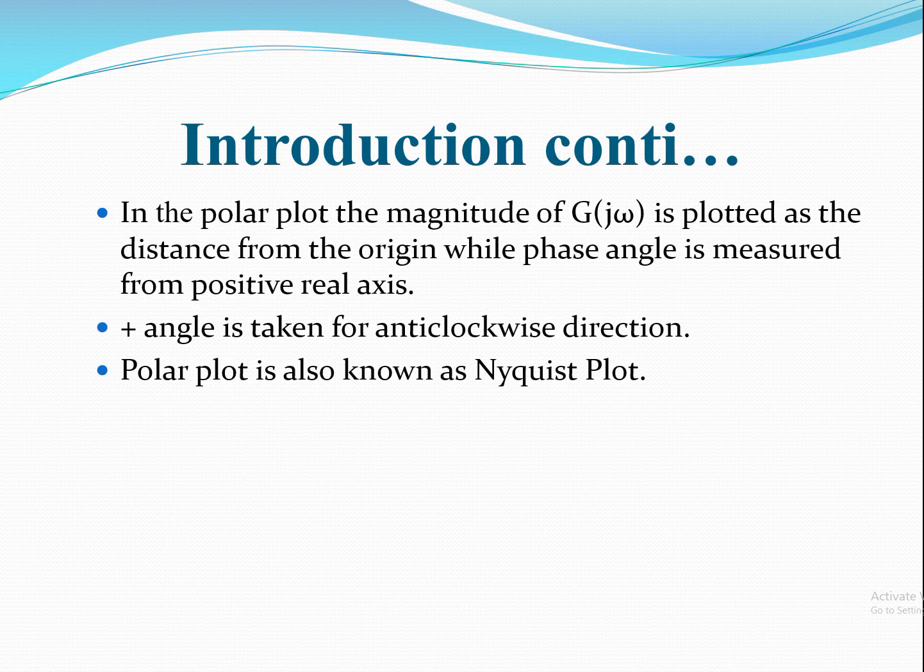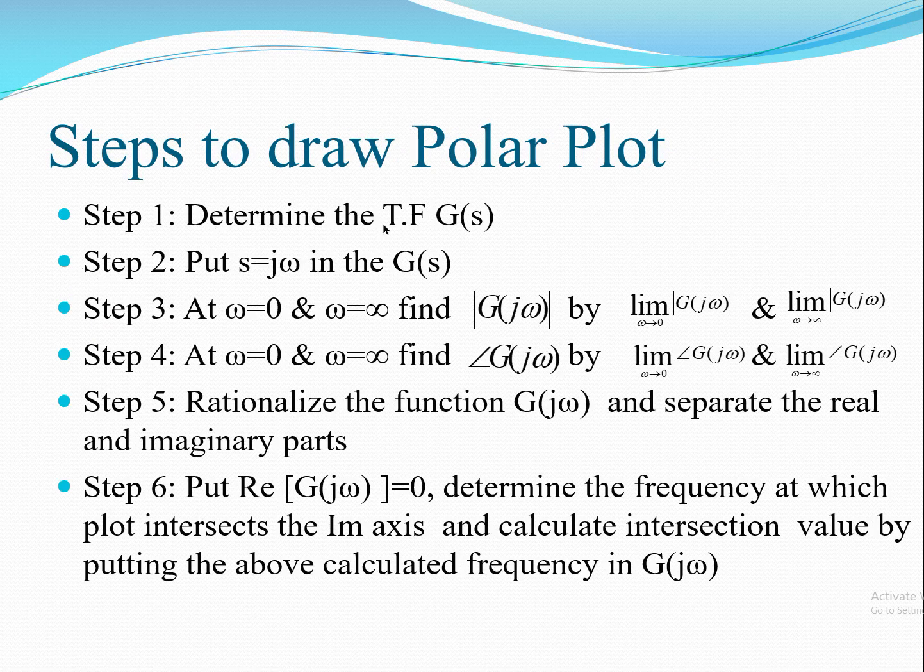The polar plot is also known as the Nyquist plot, but generally that is not quite true. With the help of the polar plot we can draw the Nyquist plot and vice versa. Once you have the polar plot, you will be able to draw the other plot. So first we will see how to draw a polar plot, and then we will find out how we can draw the Nyquist plot. First, there are various standard steps to draw the polar plot.